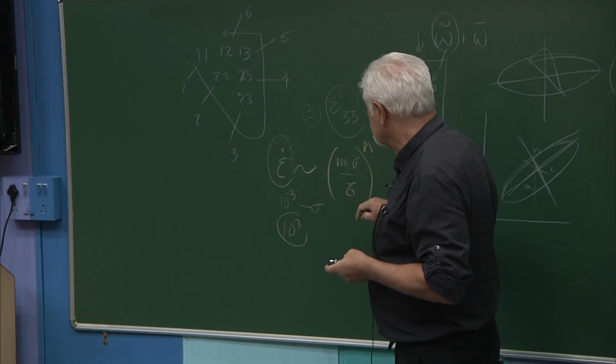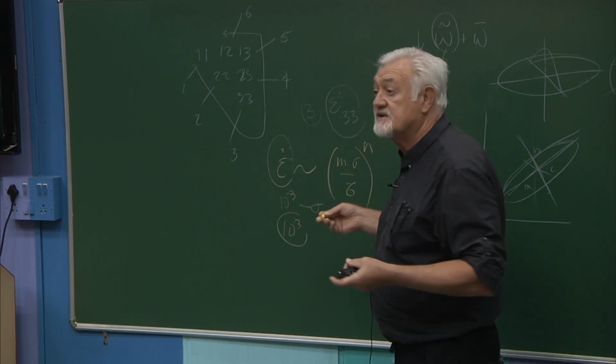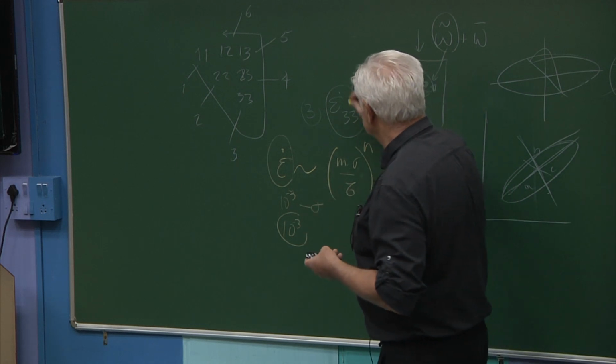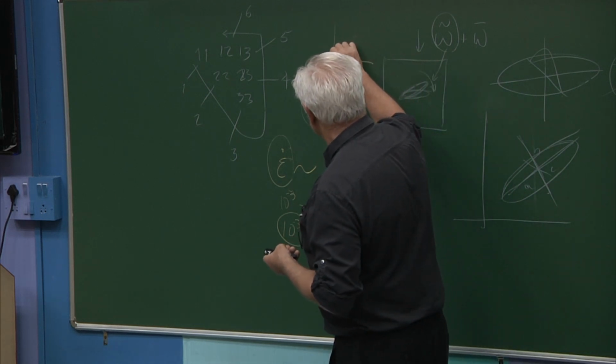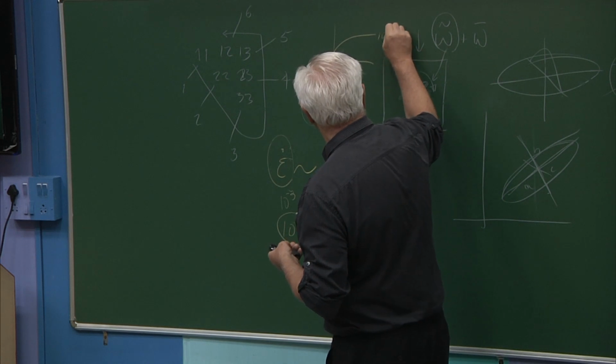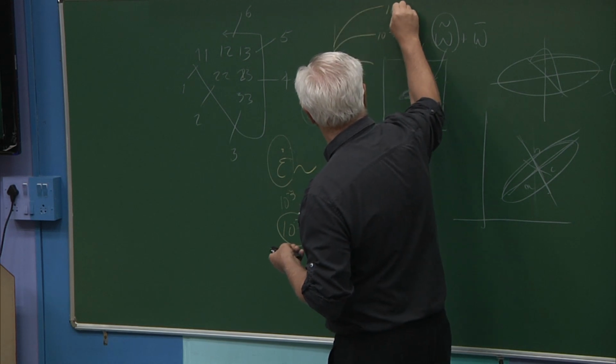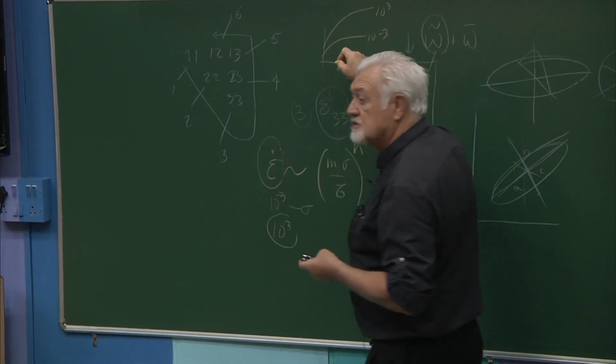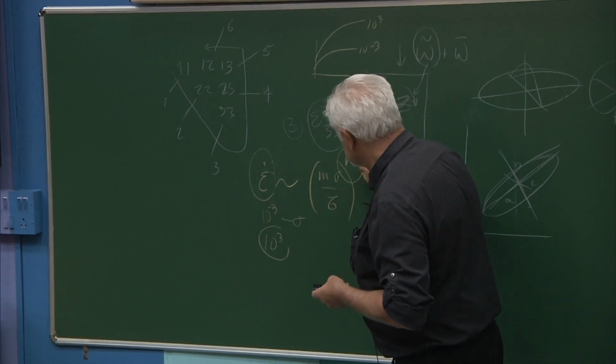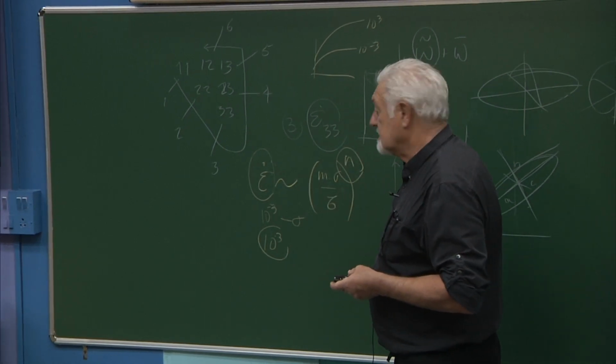And that is a rate sensitive effect. I mean, rate sensitivity is when your hardening curves at 10 to the minus 3 look like this, and they may look like that at 10 to the 3. So in order to get this effect, which is mediated by this parameter n.